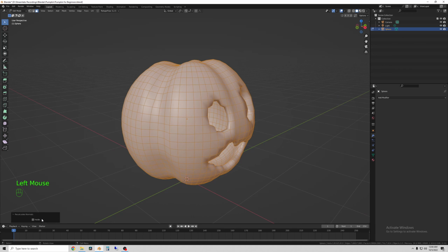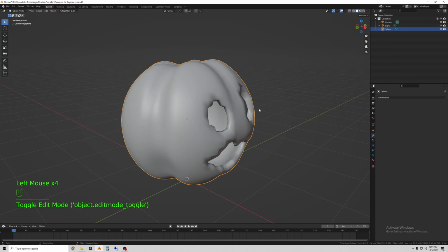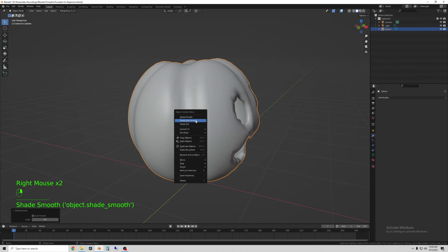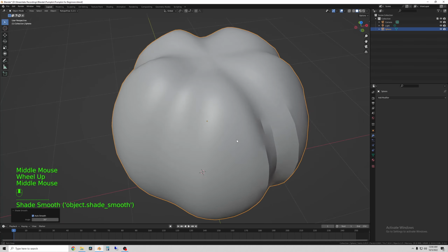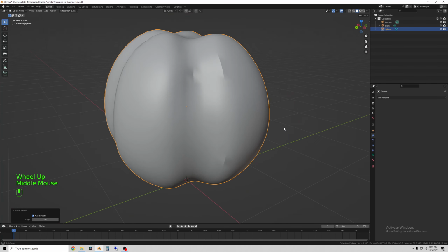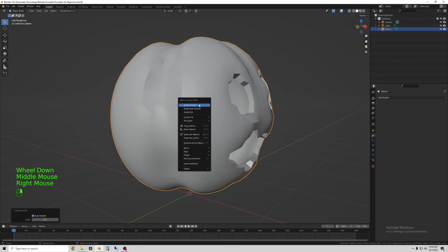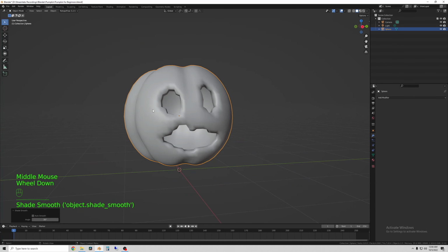So when you do that, this little menu comes up on the left. If you want to send the normals to point inside, you can, but normally don't. So just hit Shift N and then click on the screen. And most of the time that will fix those weird shading issues. So we'll shade smooth and then go back to shade auto smooth. And it looks like here, it may just be how I have the topology set up. So for now, I'm just going to leave mine shaded smooth, which is just fine.